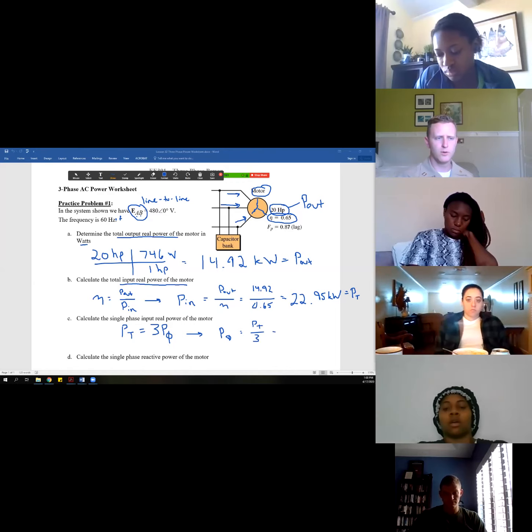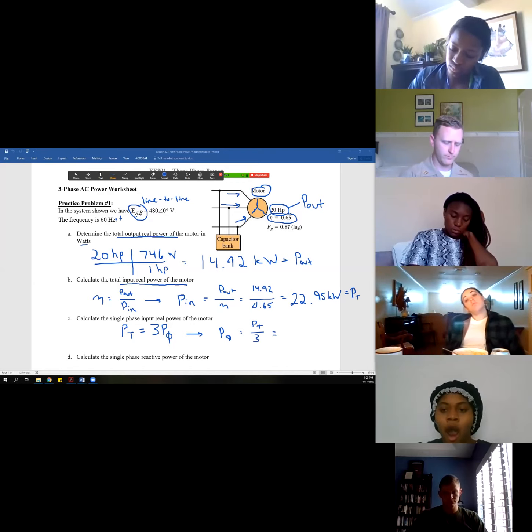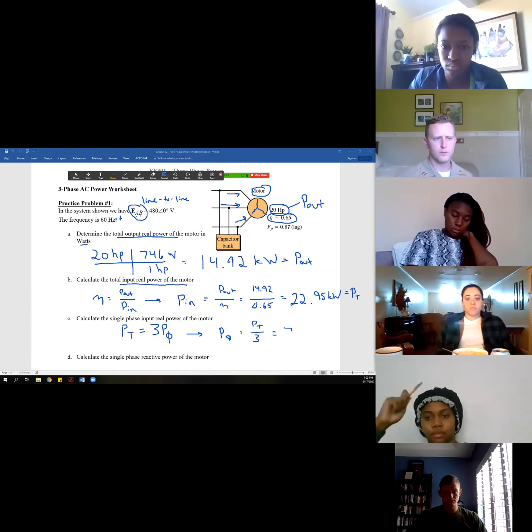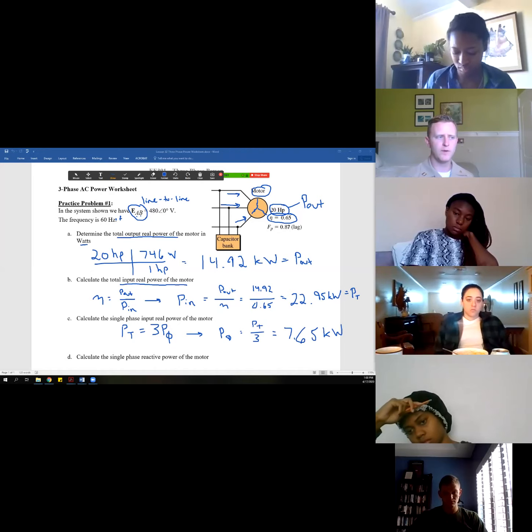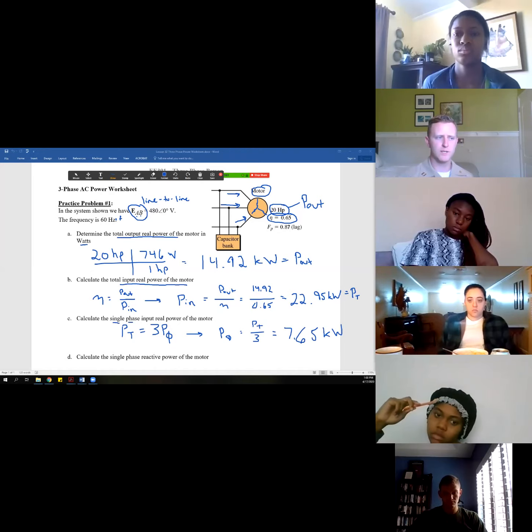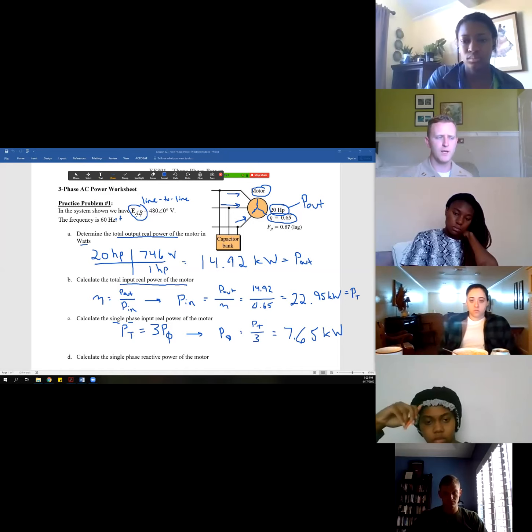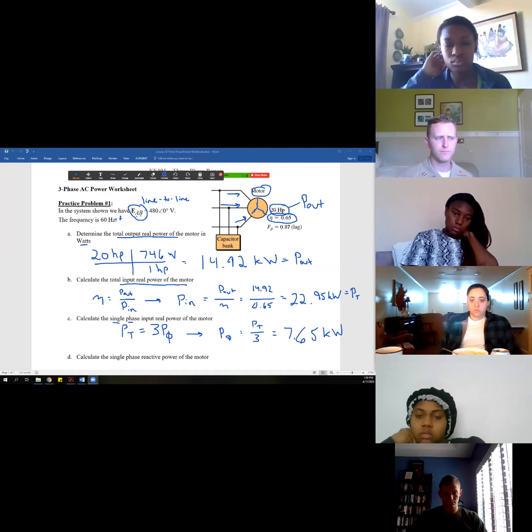P total divided by 3, 7.65 kilowatts. That is my P of a single phase. And that's what we said this phi symbol is, single phase. We've taken the input power and we've divided it by 3. Any questions up until now?